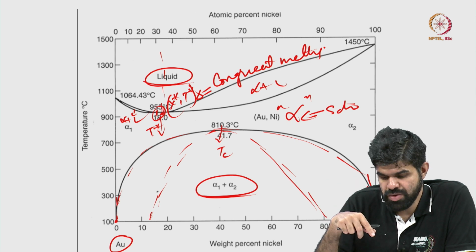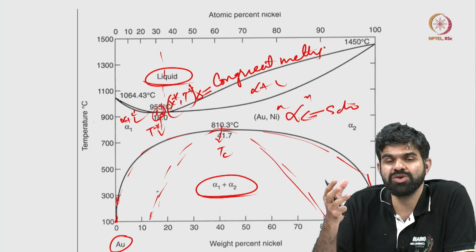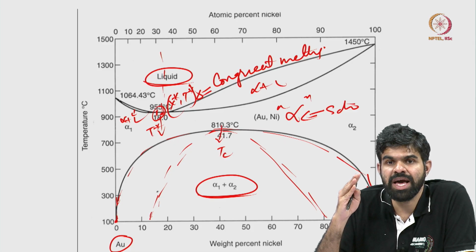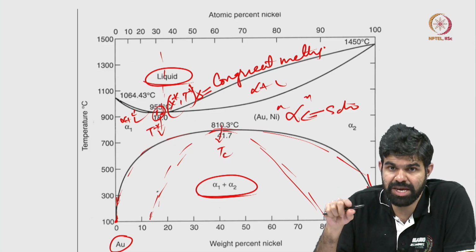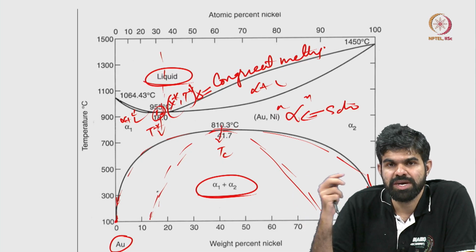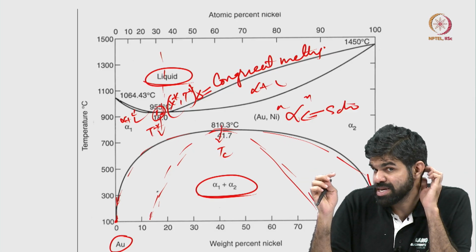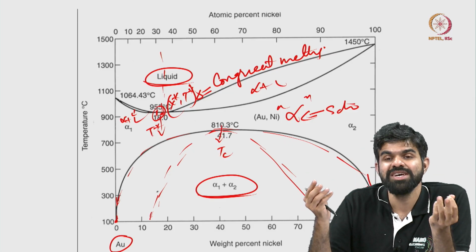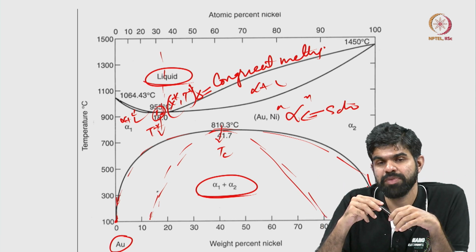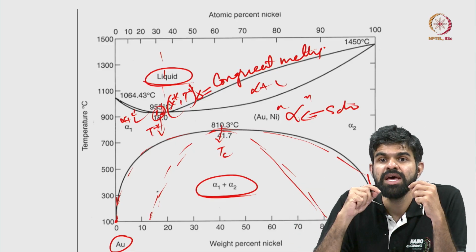And then we said later on, once you start cooling it down, there are regions where there is going to be spinodal decomposition. In those regions the alpha phase is no longer stable, it is an unstable phase at low enough temperatures, and so it will spontaneously split up into alpha 1 and alpha 2, giving rise to some kind of periodic patterns. Conversely, if you see some kind of periodicity, you can guess that there is some spinodal decomposition at play. The fluctuations just amplify, and then you get this spinodal decomposition.